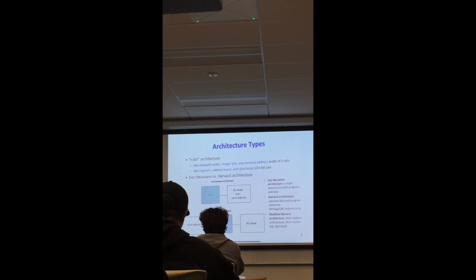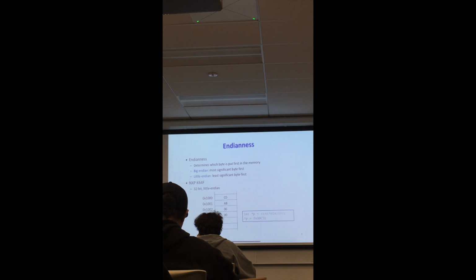That is, where program is located and where data are located. Data memory and program memory are separated in Harvard architecture, and they share the same memory space, the same memory chip, in Princeton or Von Neumann architecture. Again, it is critical. That's a classical question that they typically ask. So I do expect that I will ask again.